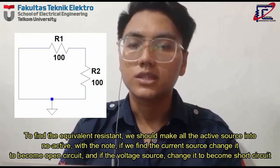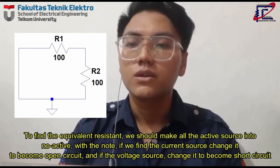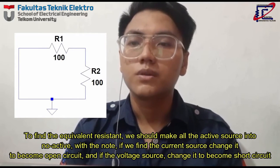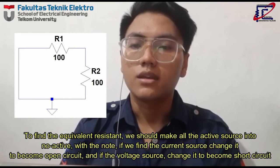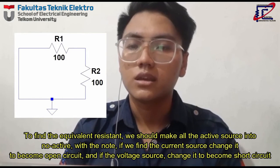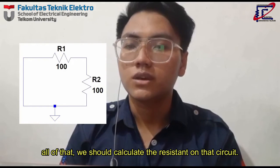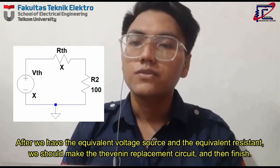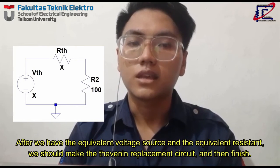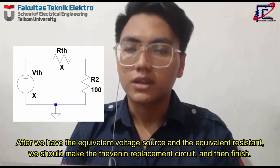To find the equivalent resistance, we should make all the active sources non-active, with the note: if we find a current source, we should change it to become an open circuit, and if we find a voltage source, we should change it to become a short circuit. After all of that, we should calculate the resistance on that circuit. After we have the equivalent voltage source and the equivalent resistance, we should make the Thevenin replacement circuit and then finish.